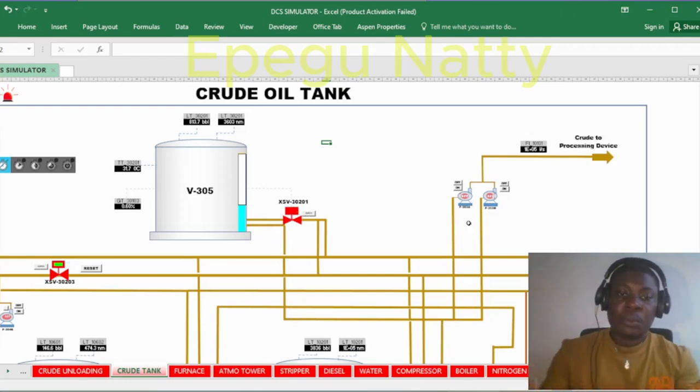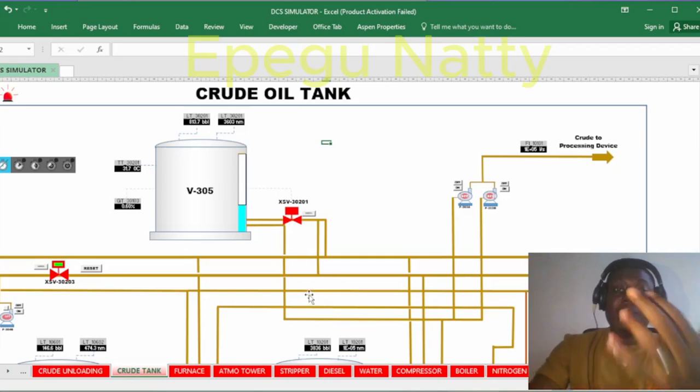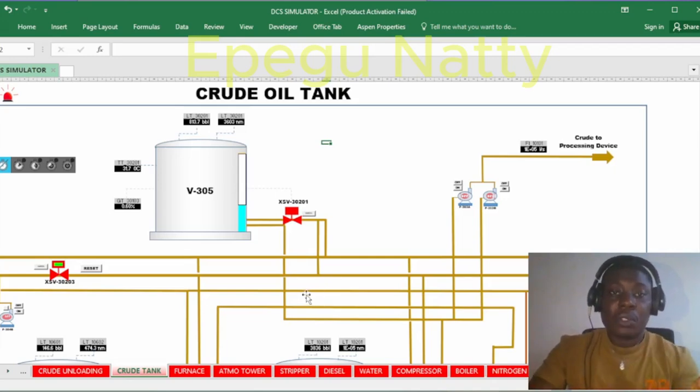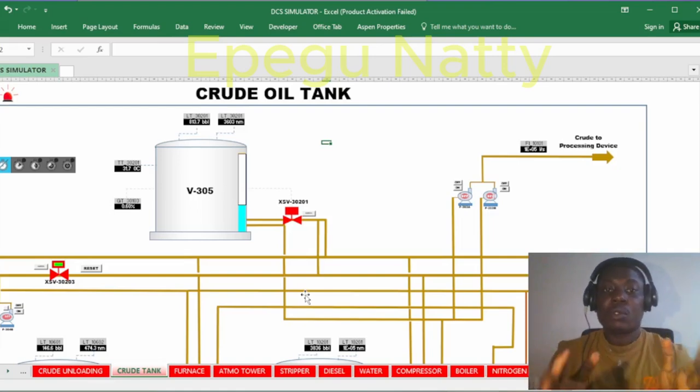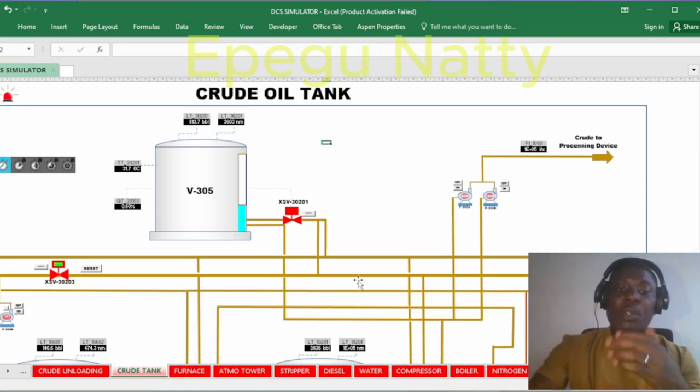Now from the control room, we are not seeing any valve going to the pump, but in the field there are manual valves. So you call the field operators and ask them to line up, that you want to carry out so operations, so they need to ensure that everything is properly lined up. When they go to the field, there is a terminal valve here. So they open the terminal valve, and then they follow the lineup. There are going to be various valves along this line.